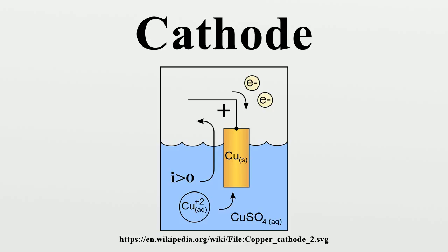Cathodes are induced to emit electrons by several mechanisms. Thermionic emission. The cathode can be heated. The increased thermal motion of the metal atoms knocks electrons out of the surface, an effect called thermionic emission. This technique is used in most vacuum tubes.